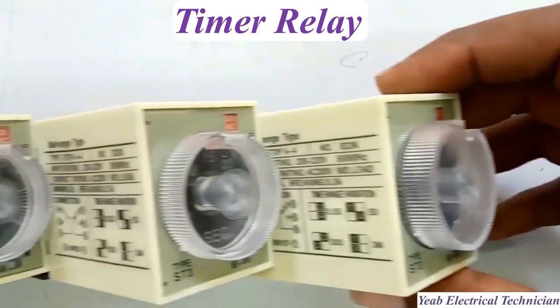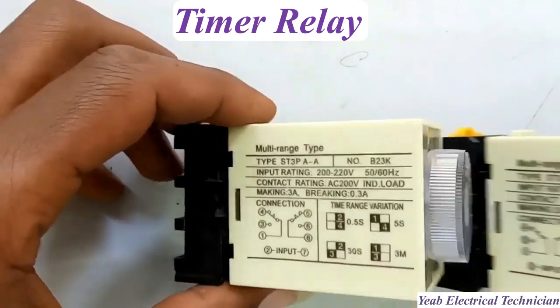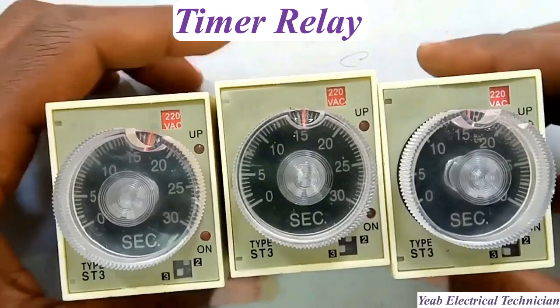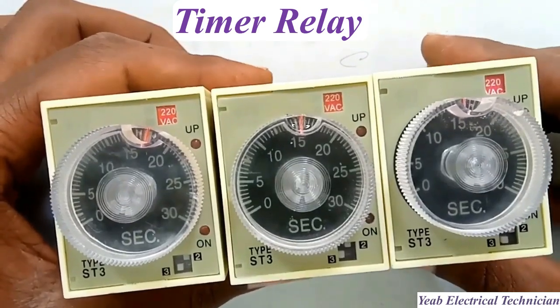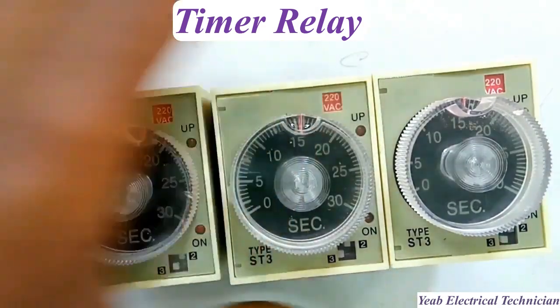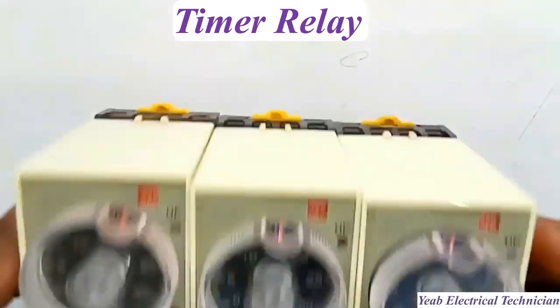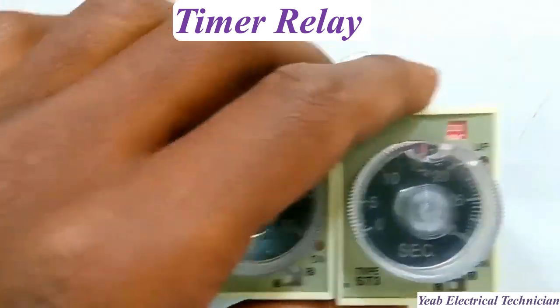An electric or mechanical circuit within the relay receives a trigger signal or input power to start the timing sequence. Once triggered, the relay waits for a preset adjustable time period to elapse. After the delay is complete, the internal relay contacts open or close to switch the connected electrical load.